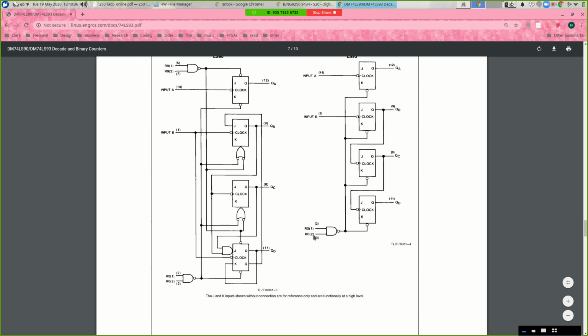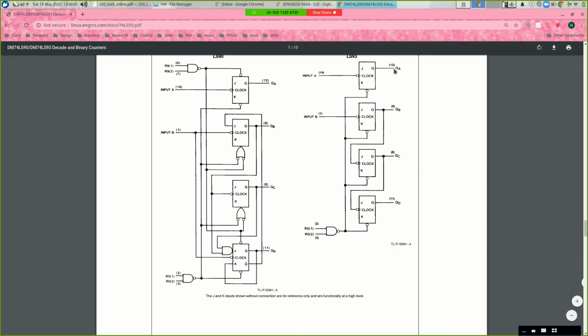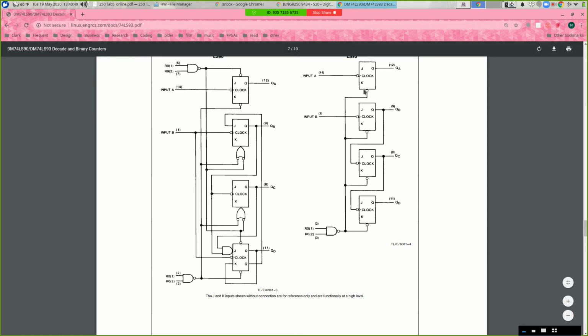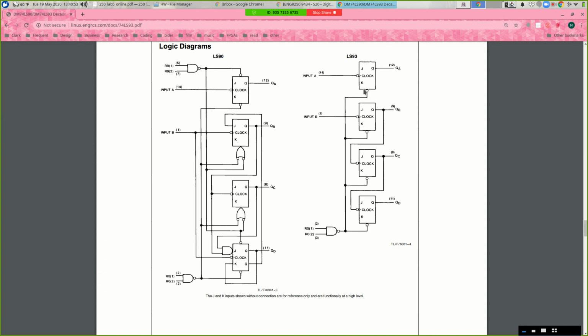Well, you can use these reset inputs to do that. So do something so that when it's at a 9, the reset line turns high, and then it will reset on the next clock tick and go back to 0. So it's implementing what you were doing in those counter questions for the homework.